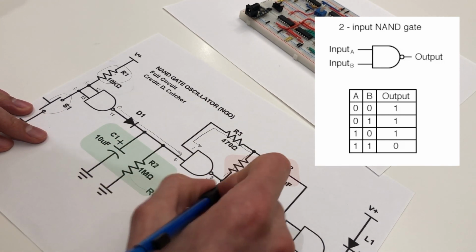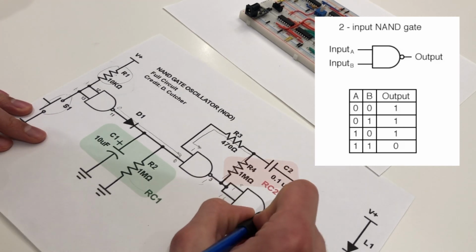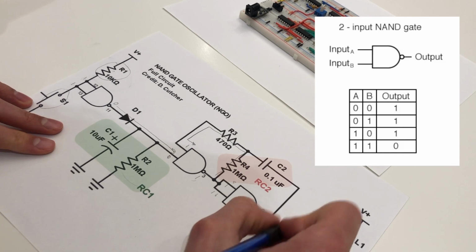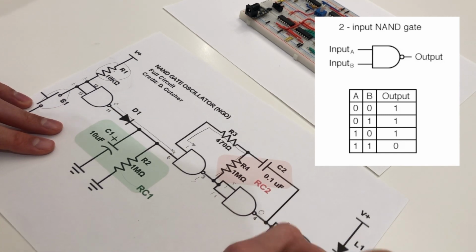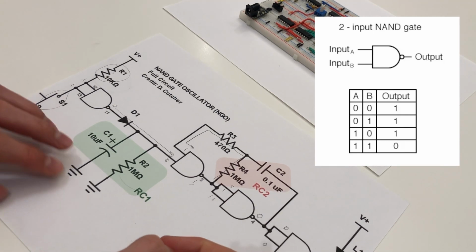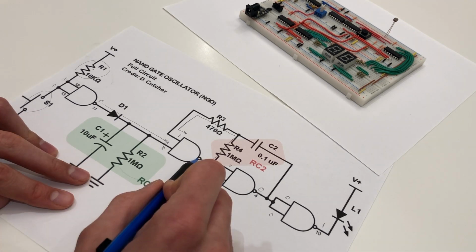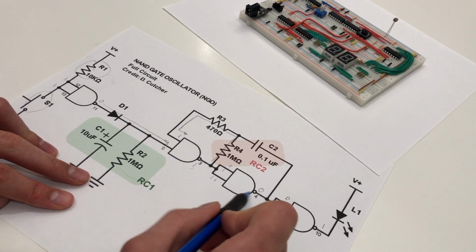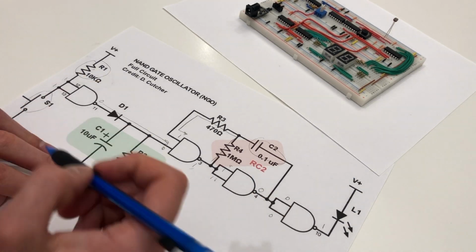Now it also goes into pins 5 and 6, making both of these high, so pin 4 is low, and pins 11 and 12 are both low, so pin 10 is high, which means that the LED is off because it has no path to ground. The difference in charges between pins 3 and 4 also charges capacitor C2 before the button is pressed.